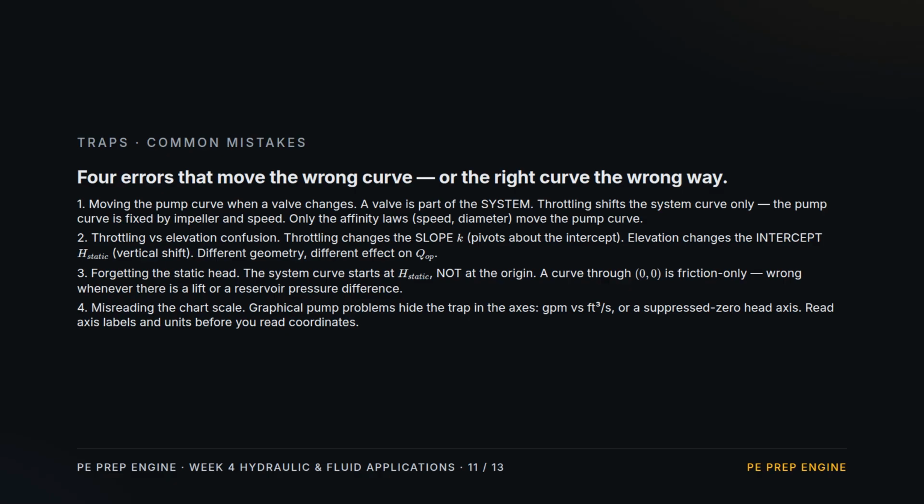Three, forgetting the static head. The system curve starts at the static head, not the origin. A curve through 0, 0 is friction only, wrong whenever there's a lift. Four, misreading the chart scale. Check axis labels and units before reading coordinates.